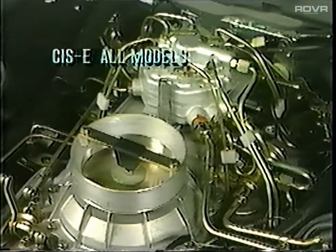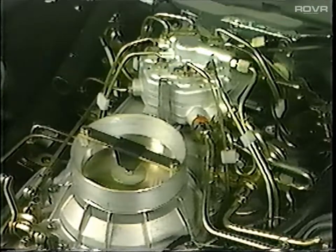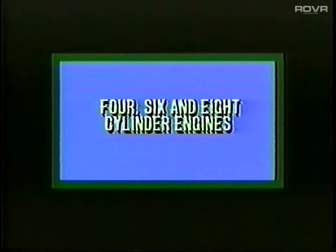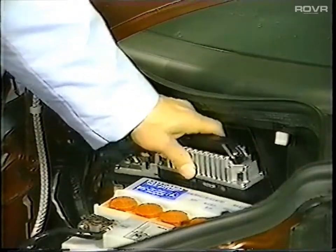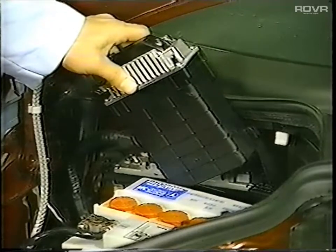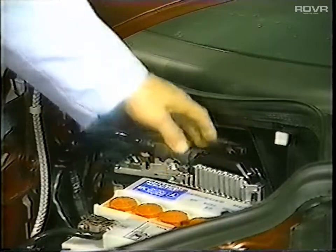Modifications have been made to the continuous injection system, the majority of which relate to all engine types. We will first review the more important changes that are common to all 4, 6, and 8-cylinder engines. There is now a federal and California version CIS-E system. New control units are used, which are not interchangeable between the federal and California version.